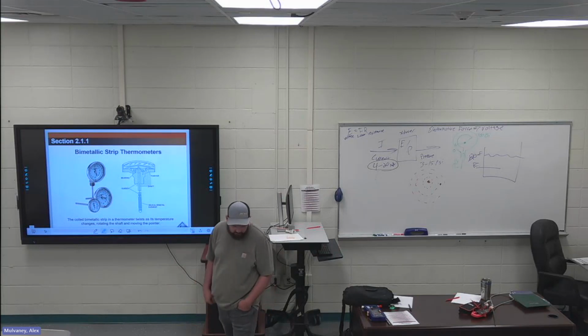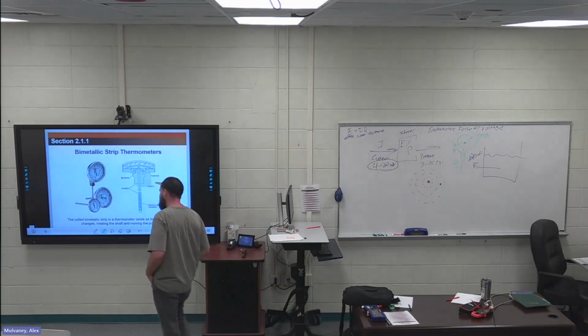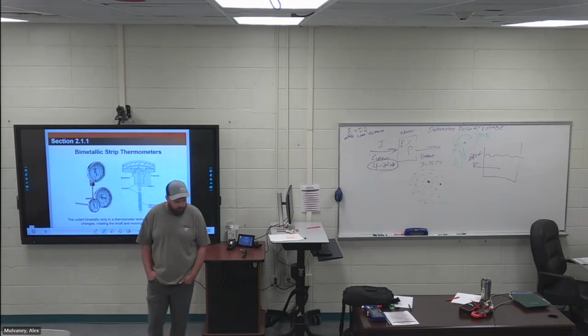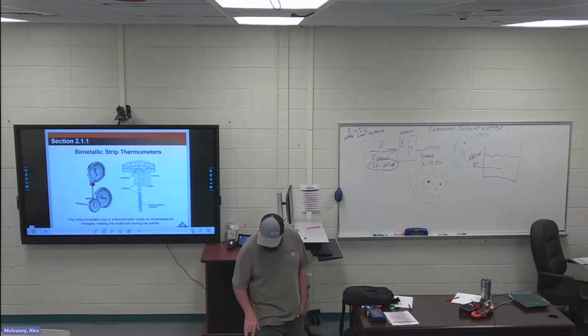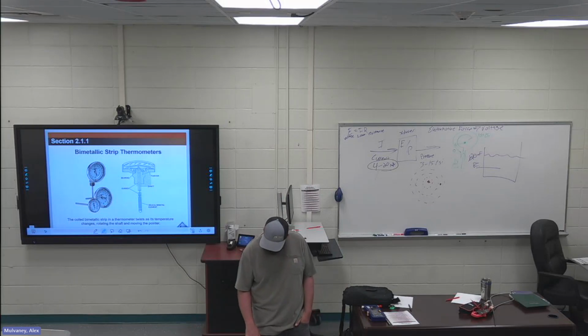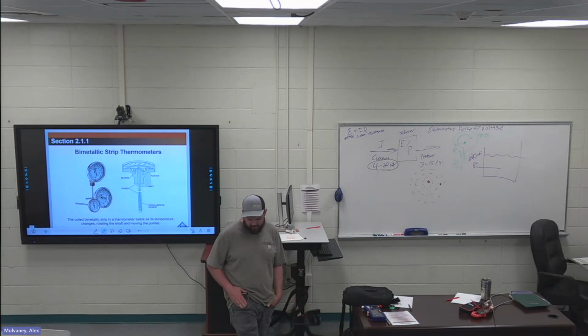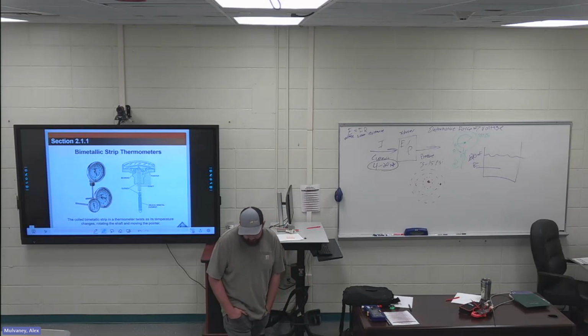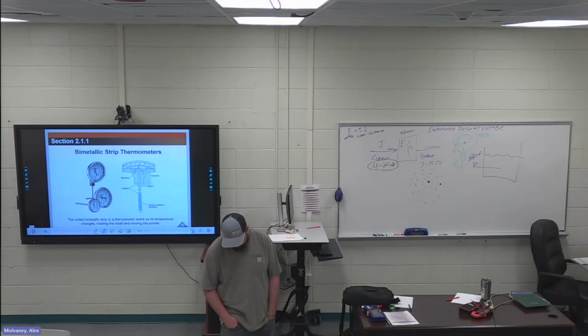Flipping over to page 18, designations for thermocouple wire. All thermocouple wire is color coded. My highlight is in the first paragraph, last sentence. To make this task easier, the International Society of Automation, ISA, has developed standard MC96-1 temperature measurement thermocouples to establish uniformity in the designation of thermocouple wire.